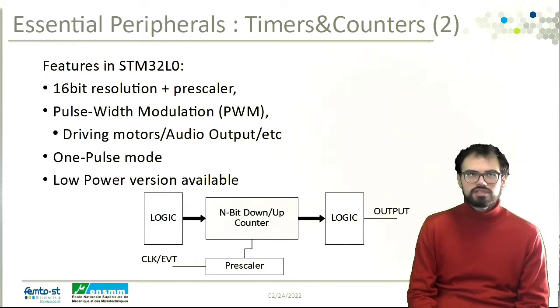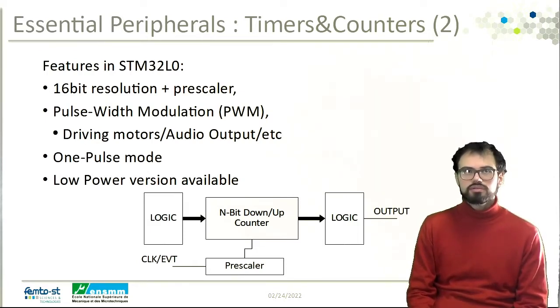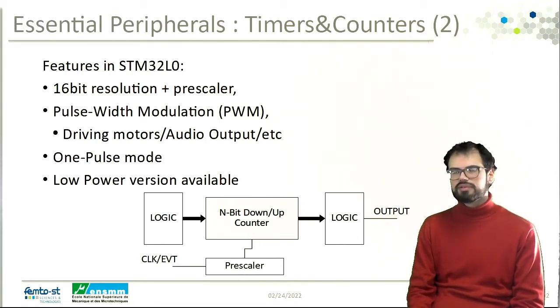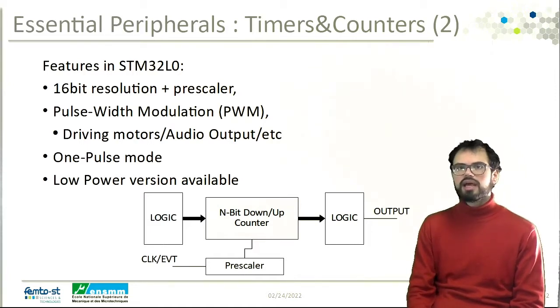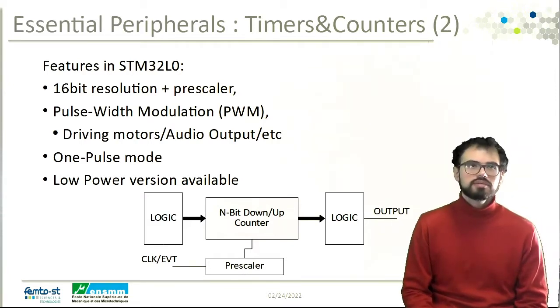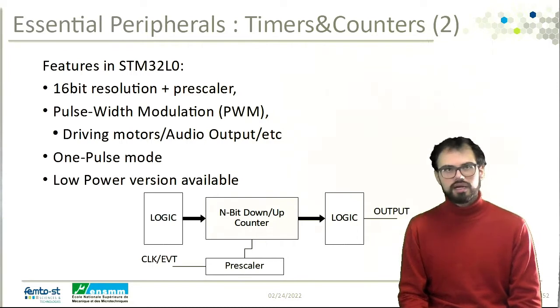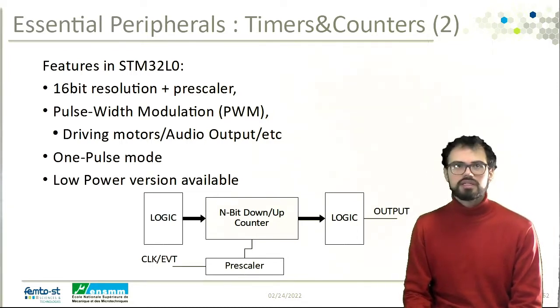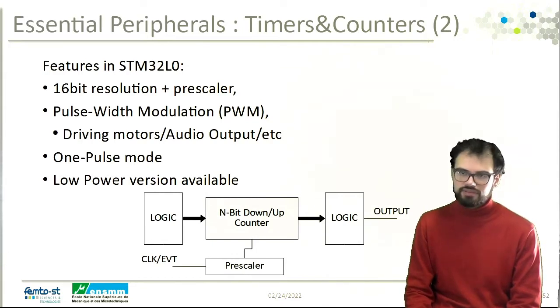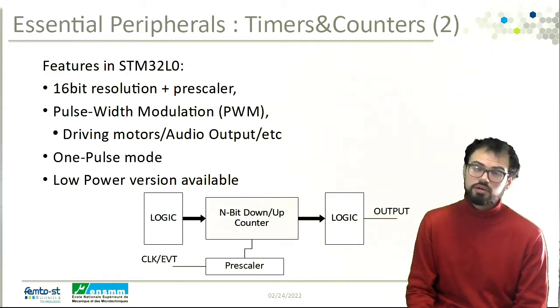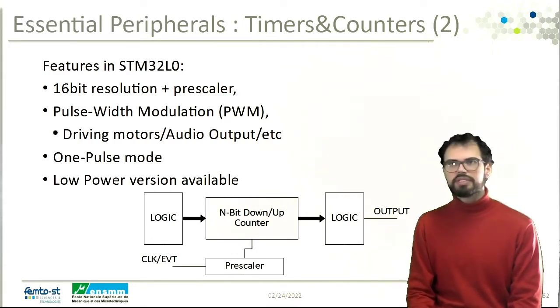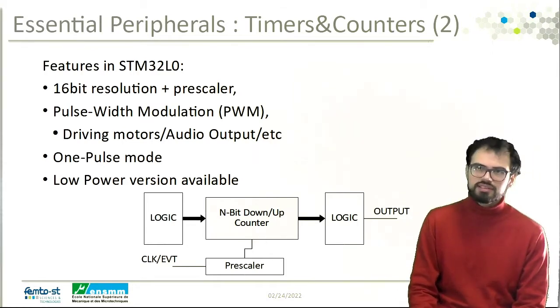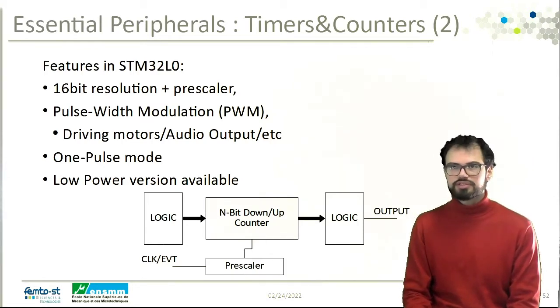Regarding the implementation, in your STM32L0 we see that you have a 16-bit resolution and an upscaler that can be more or less wide, and you have a low power version. You can even, as an output, connect to a GPIO and do, for instance, PWM modulation.